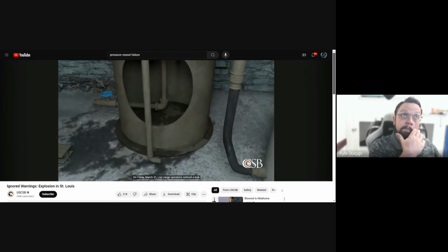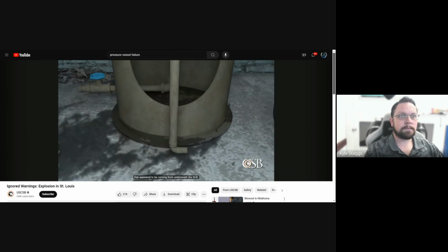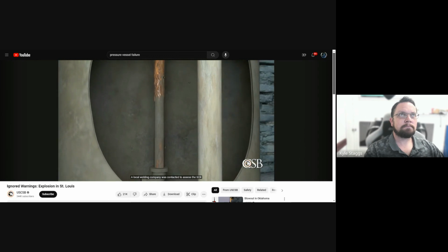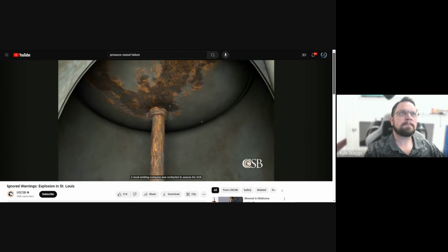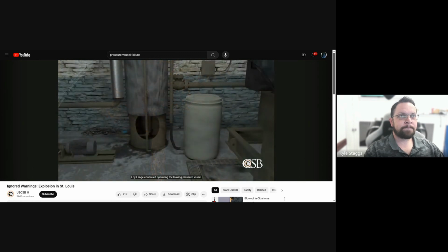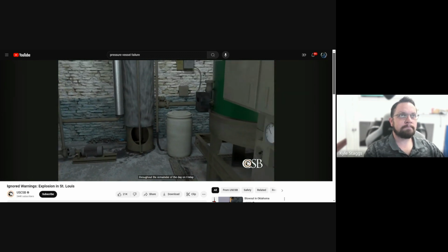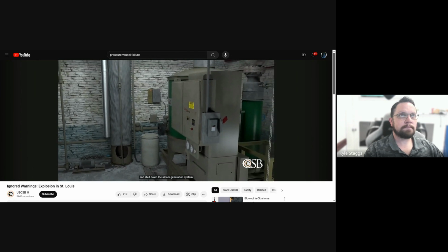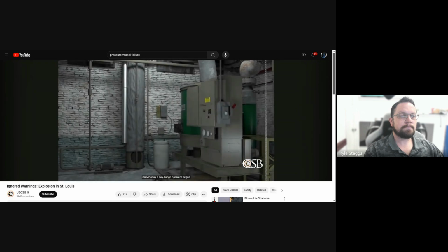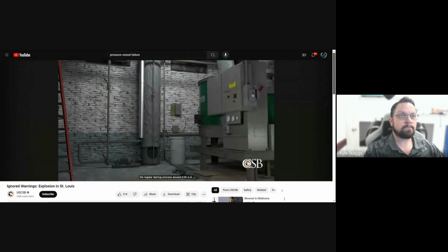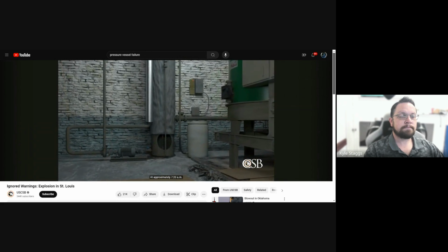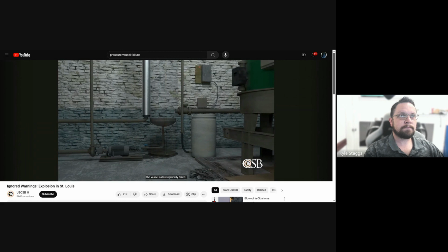On Friday, March 31st, Loy Lang operators noticed a leak that appeared to be coming from underneath the SCR. A local welding company was contacted to assess the SCR, but was not available until the following Monday, April 3rd. Loy Lang continued operating the leaking pressure vessel throughout the remainder of the day on Friday and shut down the steam generation system as normal that evening. On Monday, a Loy Lang operator began the regular startup process around 6 a.m. At approximately 7:20 a.m., the vessel catastrophically failed.